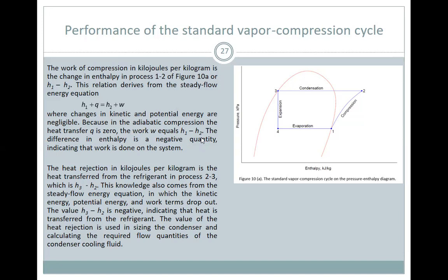Diba? So the difference in enthalpy is a negative quantity, indicating that the work is done on the system. And absolute, siyempre positive ito. Pag absolute, ginawa mo absolute. Isasagot mo, work of compression. Take note, small letter means in per unit mass.